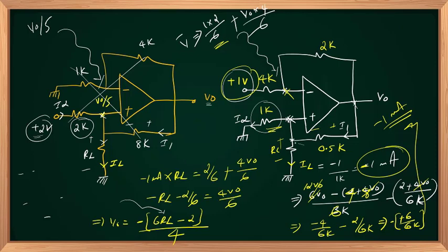The current is always minus 1 milliampere independent of the resistance RL, except for the two extreme cases, R equal to 0 and infinity. And of course these cross products are matching. So directly you can write it as 1 by 1k with a negative sign, because your input is applied to the negative side compared to the earlier case. That's all about the constant current source with a floating load and a grounded node. Thank you.